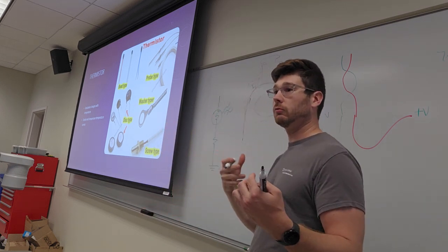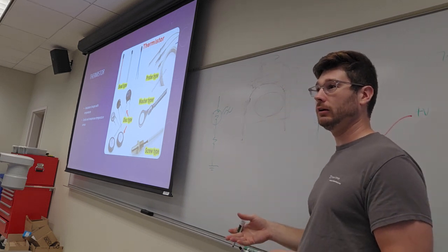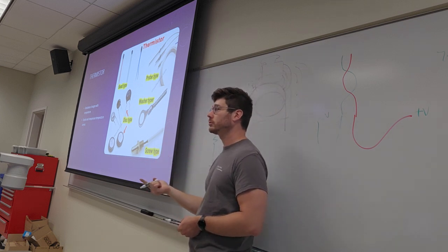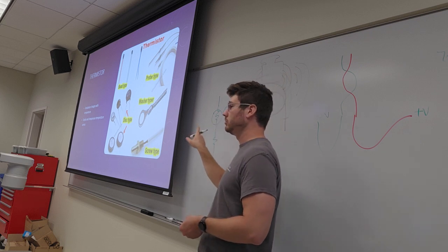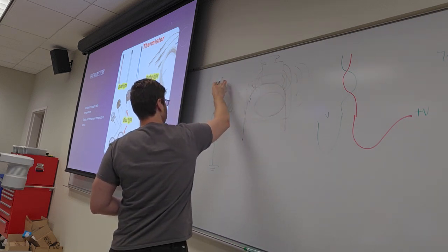But our systems don't work in kilo ohms. We can't really measure resistance directly. We have to turn that into something we can measure, current or voltage. And that again takes a little box that you plug your thermistor into, or you create this bridge like I showed you here. It does essentially the same thing.